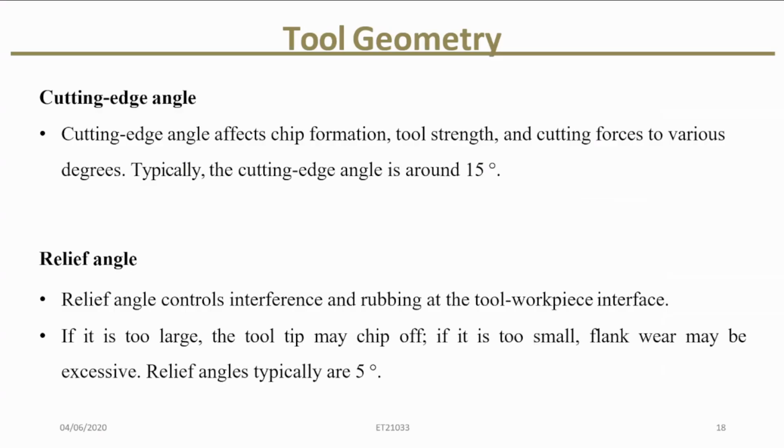Then the cutting edge angle. This is the angle between the main cutting edge and feed direction, around 15 degrees common, and the larger angles lay the chip out and reduce radial forces. The smaller angles push more into the work and can help with tight shoulders.